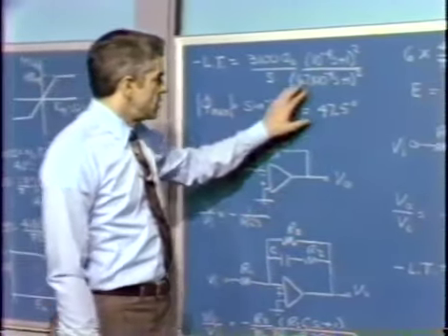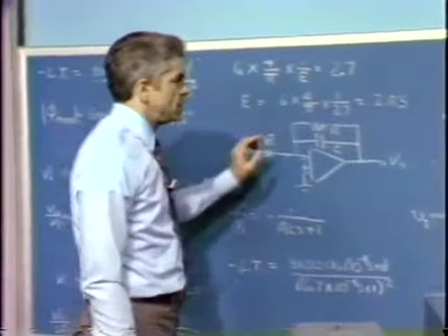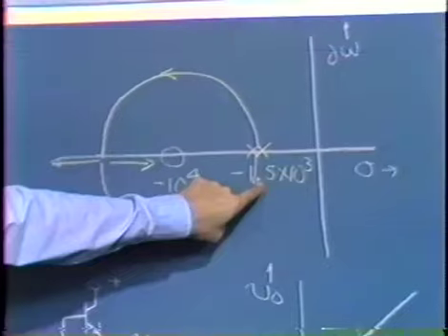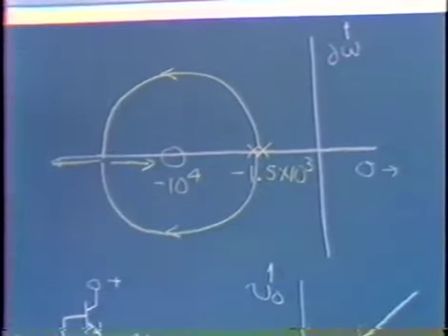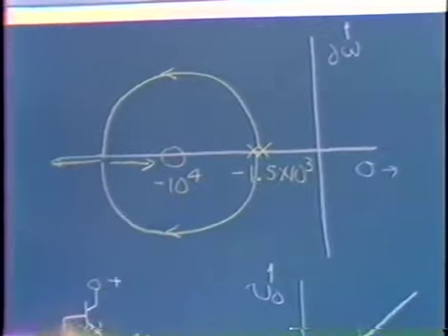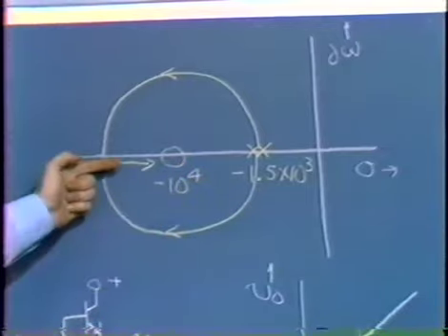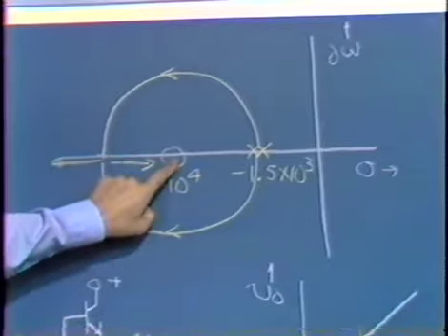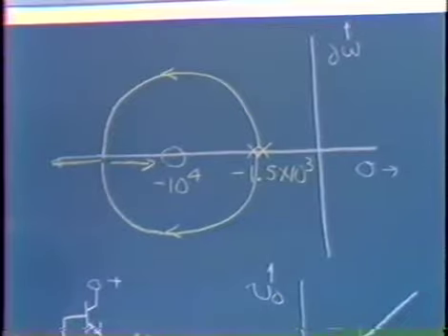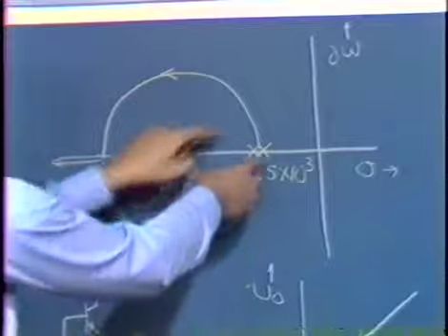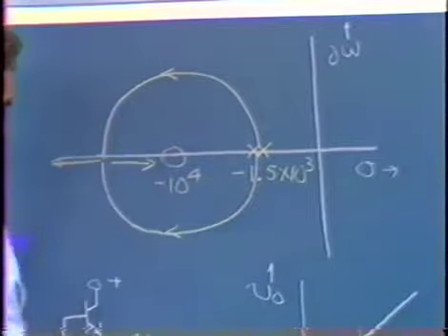The net result is that we end up with a system that has 2 poles at 1.5 times 10 to the 3rd radians per second, and a single zero now out at higher frequencies, at 10 to the 4th radians per second, because the pole that replaced the pole at the origin cancels one of these zeros. The system's now absolutely stable. There's no value for the A0, F0 product that gets us into trouble. The root-locus diagram for the system is as shown.